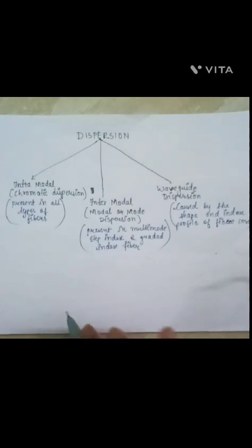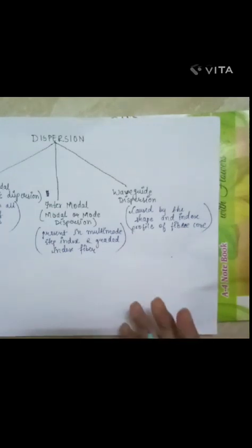When the pulse is sent, parts of the pulse take many different modes, and therefore some components of the pulse will arrive before others. This difference between the arrival time of light taking the fastest mode versus the slowest obviously gets greater as the distance gets greater.